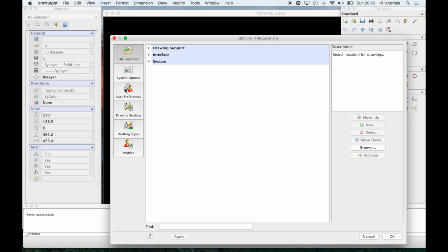And if you want to move something a set distance away from an existing object, the only way I found of doing that is to drop a guide in, drop a second guide in, double click on each guide, find out what their coordinates are, calculate the coordinates manually, edit the guide position, and then you can draw something aligned with that guide, which is time consuming and I don't find very user friendly. So I'll show you how AutoCAD and Draftsight allow you to draw stuff accurately.